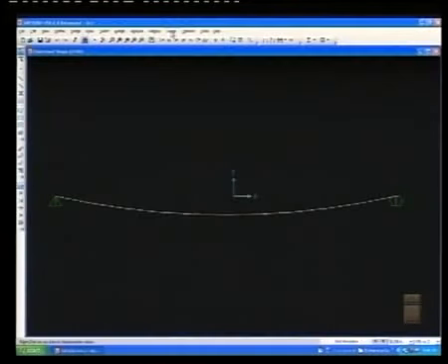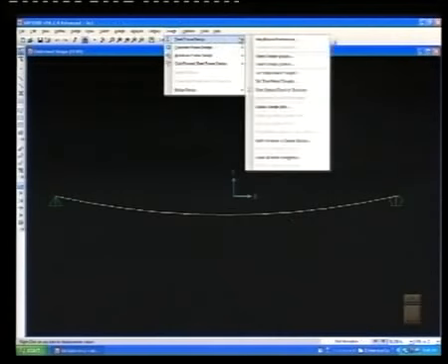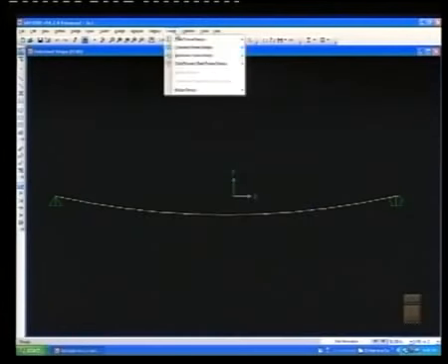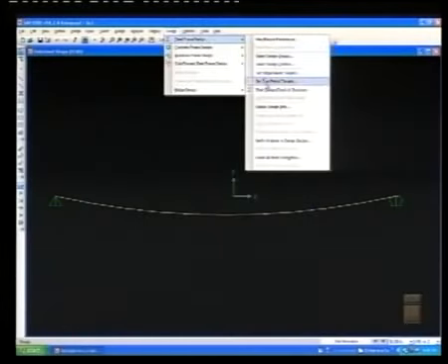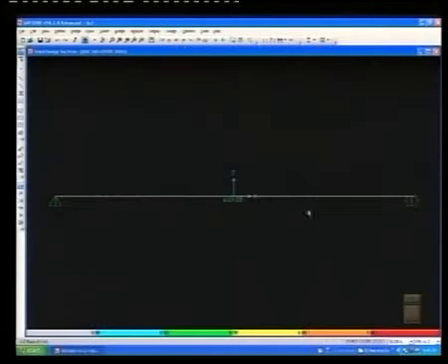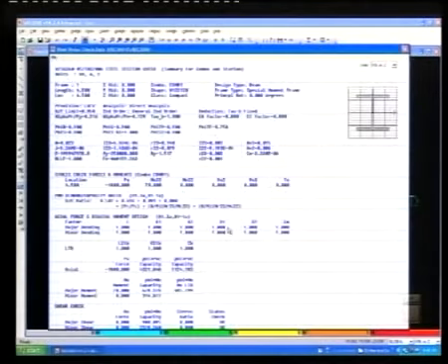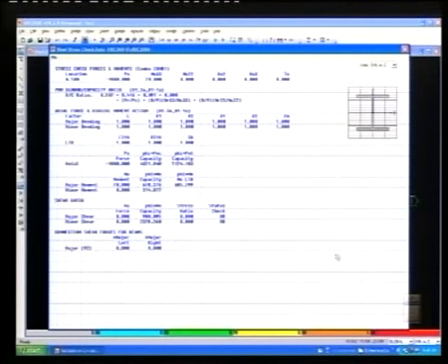And in design, we go and we say select design combination. We need combination 1 to be added. We don't want any other combination. We say okay. We do the design. And now we get the same value we got, which is 0.507, and now the details are the same as what we had, but now M ultimate, the ultimate bending moment, is 70, not 90.